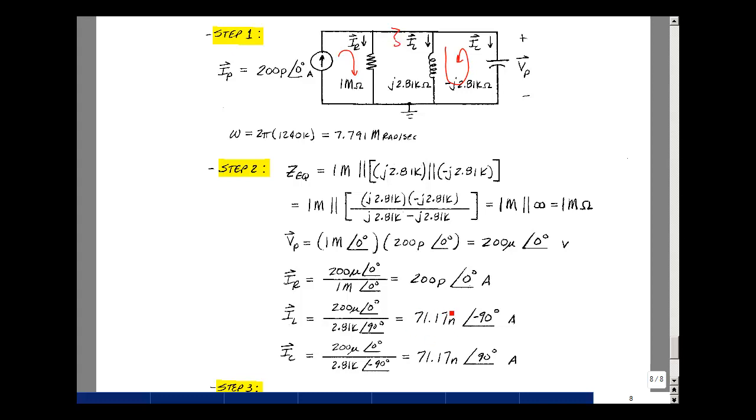Now this current is about 356 times bigger than this current over here in magnitude. So like we saw for series resonance, where we could create very high voltages from a particular voltage source, here we can create very high currents from a current source. Now if we add up all the power, it still sums to zero. Whatever came in went somewhere. We're actually stepping the current up here, whereas in the series resonant case we were stepping the voltage up.